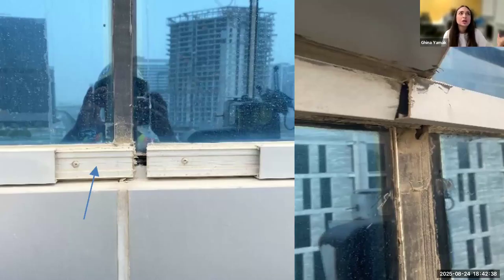We see it a lot. We see it a lot also in stone facade, where panels are falling, panels are breaking. What's the reason? We go there, we inspect, and sometimes there's absence of fixing. Sometimes some facades are fixed with a mechanical fixing, proper one, and then the rest of the facade is fixed with the wet fixing, almost just hanging there. So it's just a poor installation on site.